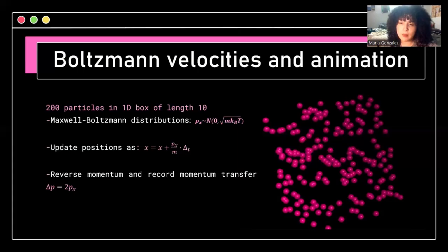The cool part is that technically, as I told you, this is a 1D system. So I added fake vertical y coordinates, spreading them along with the positions I was getting from the simulation. In this way, I was able to display it in a 2D environment to actually see it and export it to VMD. Otherwise, it was all stacked on top of each other and we would not be able to see what's happening. At every time step, we updated the position of each particle using Newton's second law: position plus velocity times delta t.